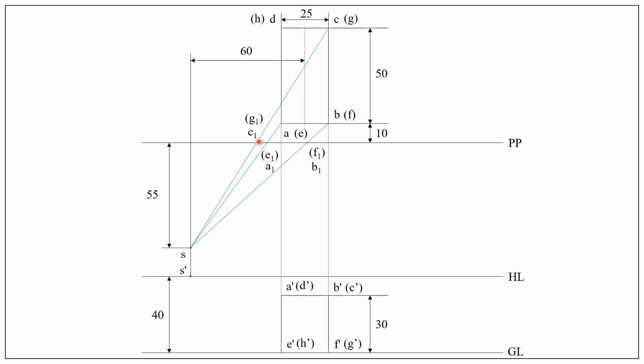because at this corner we have 2 points, one is C, another one is G. So C is at the top of the prism, G is at the bottom of the prism. Therefore, we get two piercing points. Finally, connect S with D. So also this point represents H. So the line from S to D, or the visible ray from S to D, pierces the picture plane here, and that point is D1 H1.